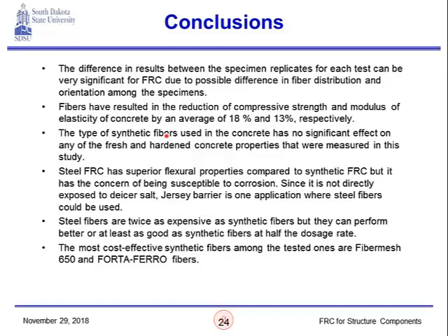That's for synthetic fibers only, but once we looked at the steel fibers, we can see some notable increase in the flexural performance. Again, this is most likely due to the fact that steel fibers have very high tensile strength, and all the synthetic fibers had comparably very close tensile strength to one another.